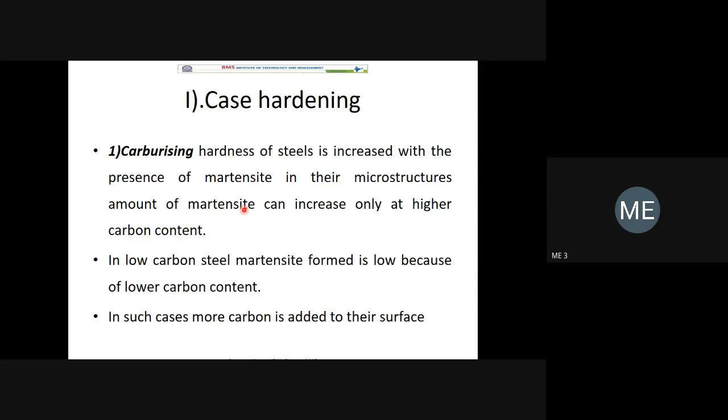No, it is not possible. There are a lot of technical challenges. Imagine you have iron, steel is there. You are adding carbon. You are mixing it. It is in the molten state. You cannot move only the carbon atoms towards the outer surface of the specimen, or during solidification, the carbon atoms will rearrange themselves. We cannot force them to go and occupy only the surface of the material. That is not possible.